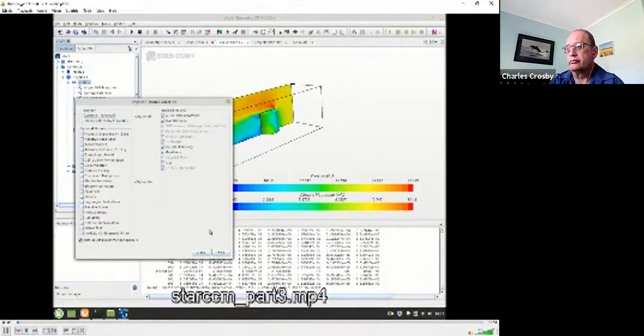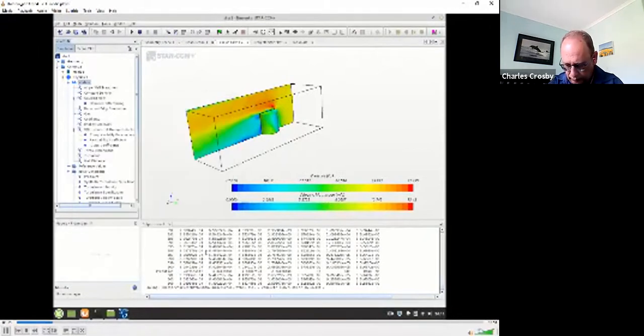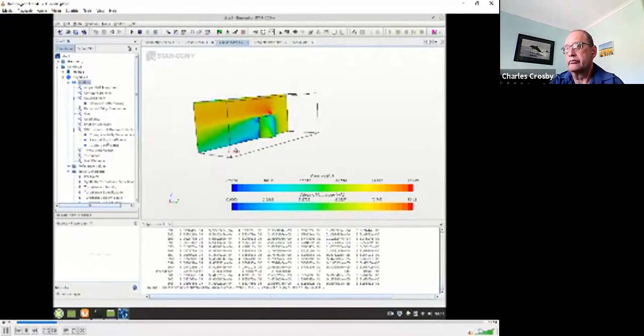As an experiment, we've now switched to a transient simulation, but this time we are going to be using the K omega detached eddy simulation model. So it's a lot more sophisticated on the physics that it's modeling, and it's going to be much slower. We're starting from a fairly good solution that we already had. We're using appropriate discretization scheme, and let's start running.